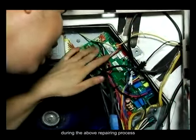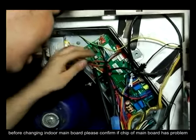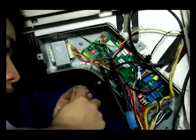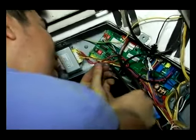During the above repairing process, before changing the indoor main board, please confirm if the chip of the main board has a problem, or the pins of the chip have fallen off, or the chip is installed in the opposite direction. The correct installation should be according to the direction of the half round.